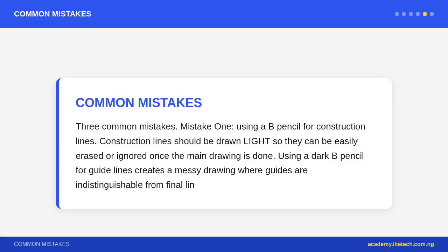Question 3. What is the difference between a compass and a divider? A compass has one needle leg and one pencil/lead leg. It is used to draw circles and arcs. A divider has two needle legs, no pencil. It is used to transfer and compare measurements, and to divide lines into equal parts. Both look similar but serve different purposes.